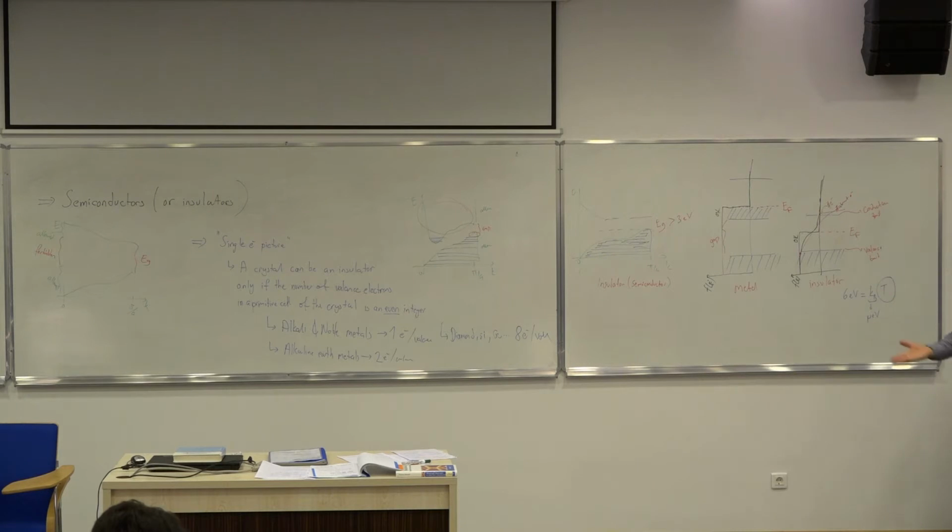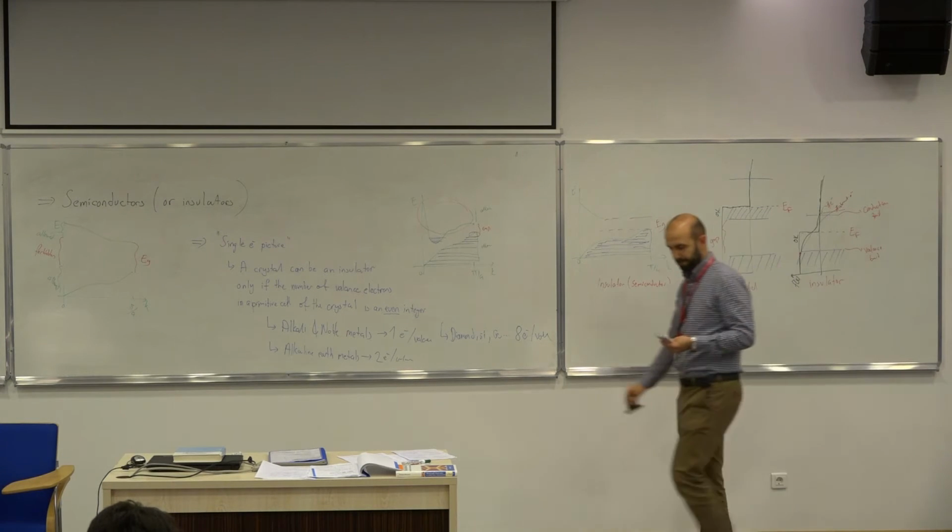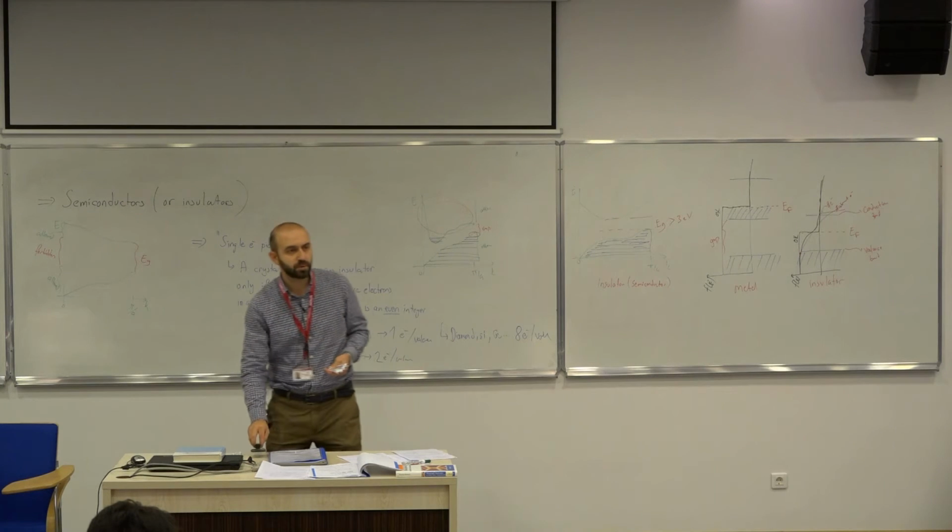But you can do this easily for silicon. You can start from 0 Kelvin. Silicon is a very nice insulator. As you increase the temperature, of course, there are other effects. But what you'll see is there's this carrier freeze-out zone. So electrons are not available. And then you'll enter a regime where it will start conducting. So this is a simple answer to your question. Any other questions?